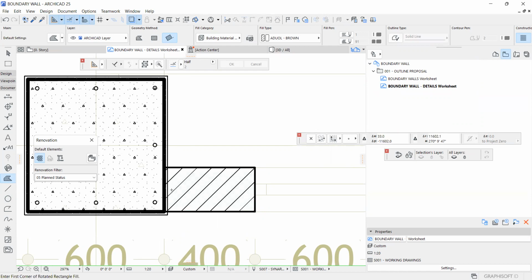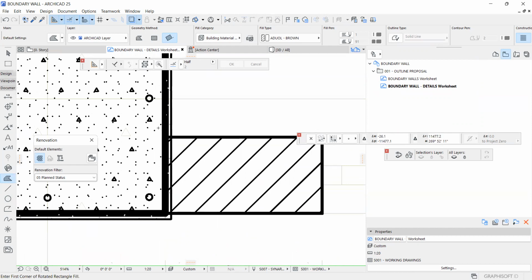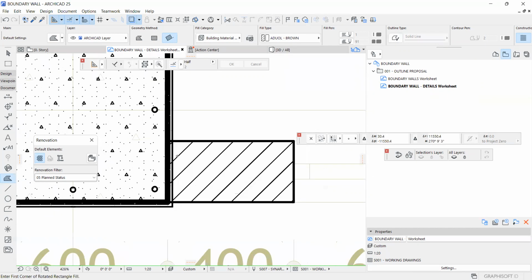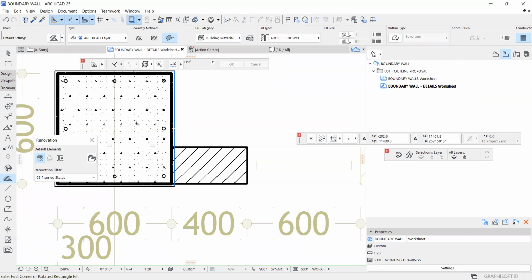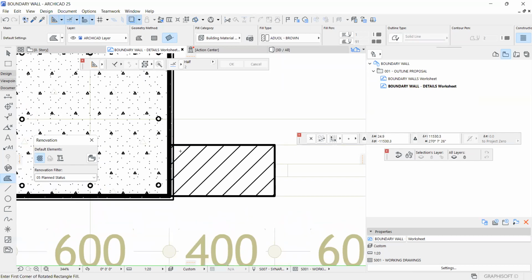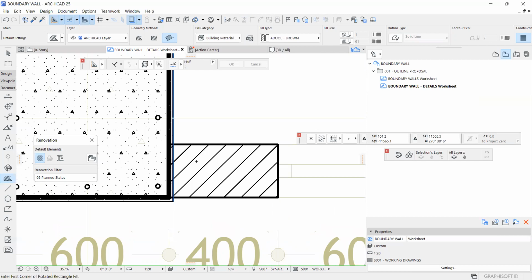Now, a rule of thumb, you'll never plaster on a masonry. If you're building in a systematic way, you'll start first of all with the column, then build the masonry, and come and plaster. What does that mean?